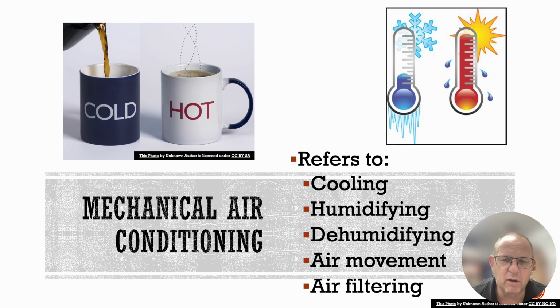Now, when we're dealing with mechanical refrigeration, there's a couple of different aspects of it that go into it. We are really referring to the cooling, the dehumidification of the air when we're dealing with air conditioning, and air movement that is not being uncomfortable for the occupant that's in that room. And honestly, when an air conditioner is running, we should not be able to hear that air conditioner run if the ductwork was sized correctly and the unit was sized correctly for the house itself. So air movement's very important.